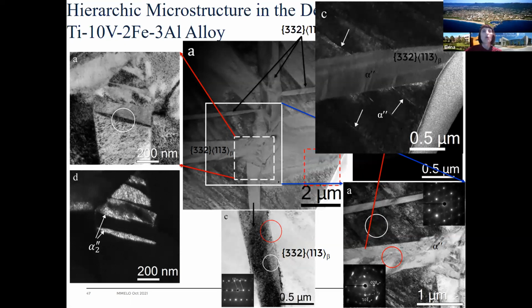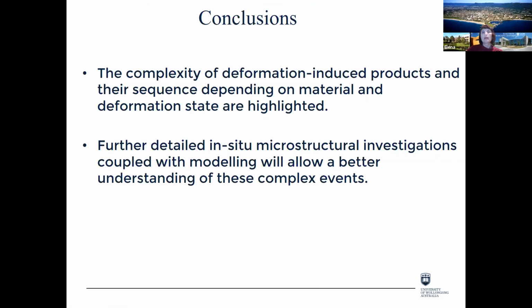during deformation of titanium alloys, which depends not only on the composition of the alloys, the stability of martensite, and whether it reverts on unloading, but also on the stability of beta phase, on the stress state caused by different load conditions, strain rates, or change in the strain path.